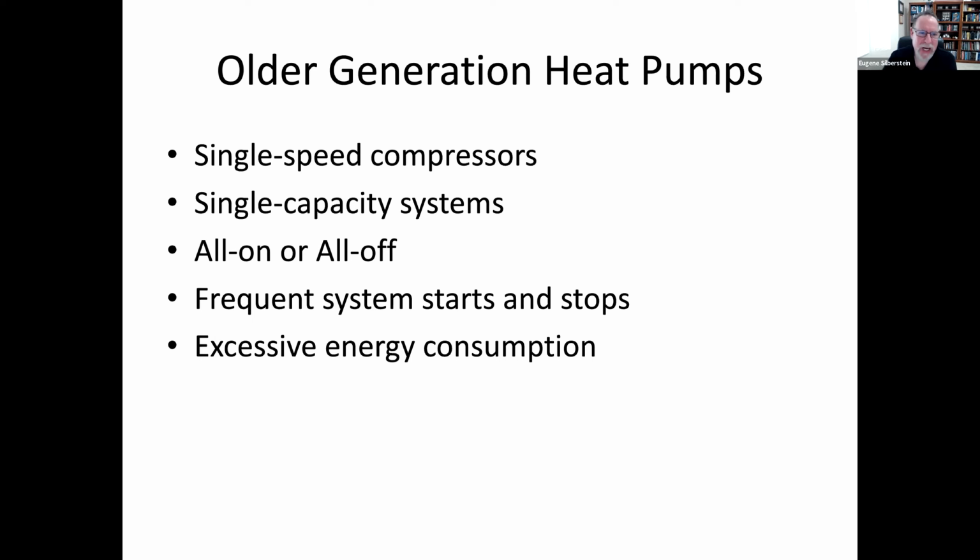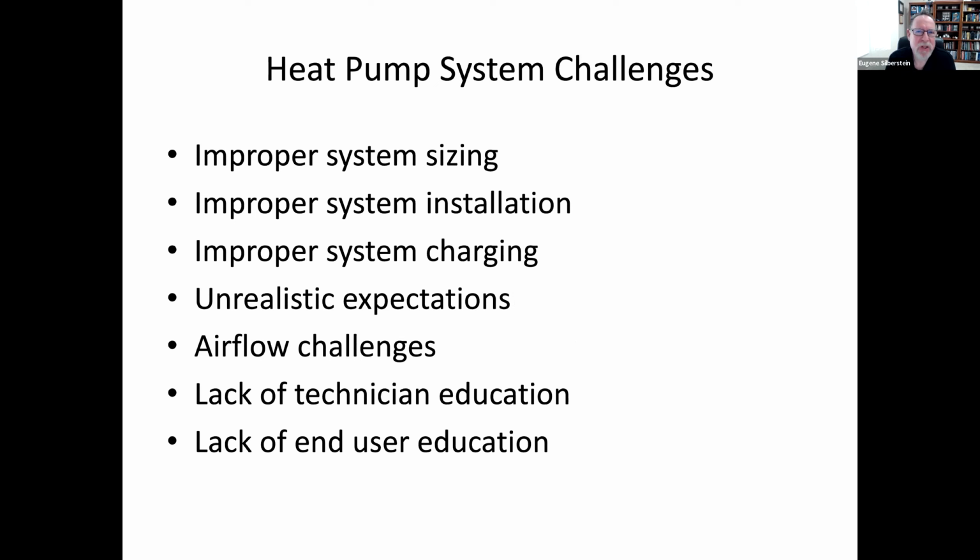So whenever our heat pump called for heat, we were getting vapor compression heating as well as second stage electric heat. So some of the challenges that we're facing with heat pumps are improper system sizing, improper installation, improper charging, unrealistic expectations of what the heat pump system is going to do.